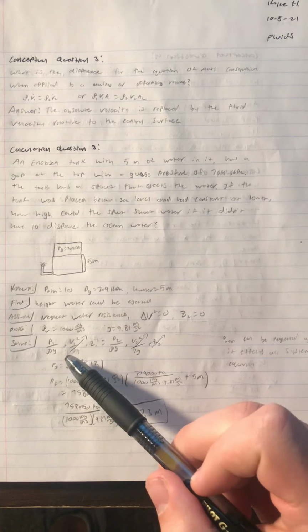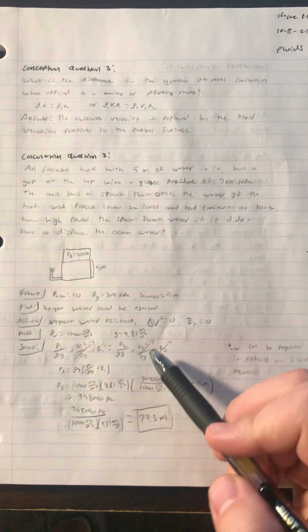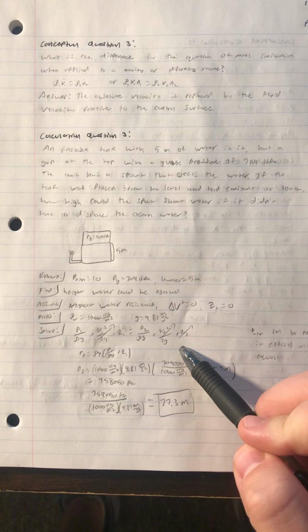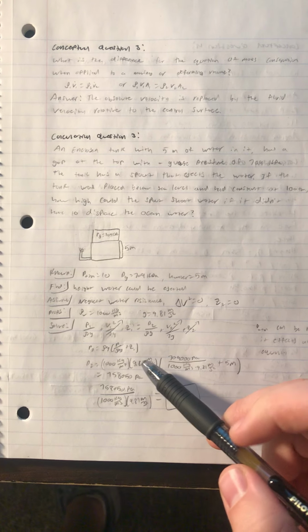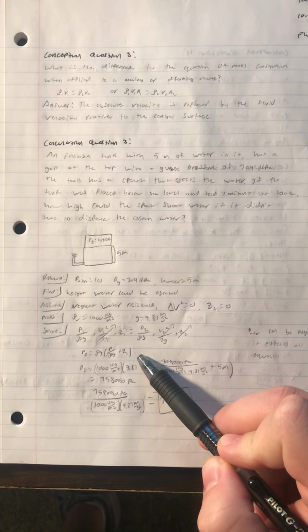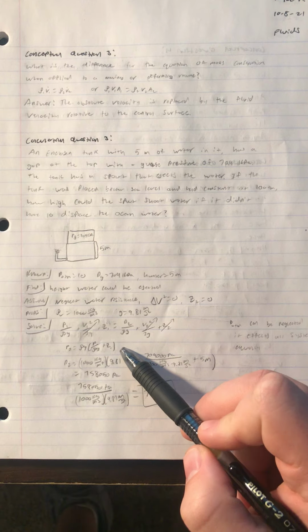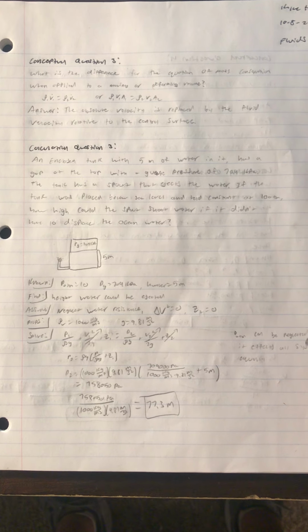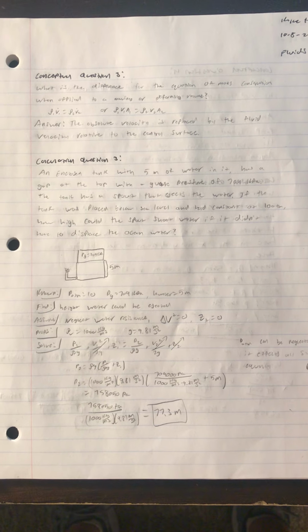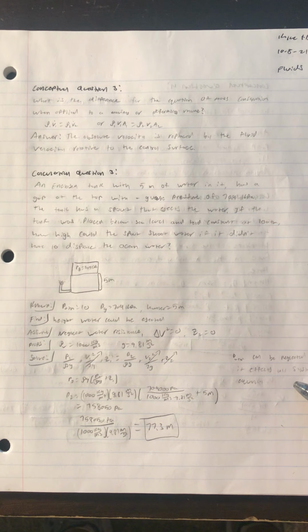So we go to Bernoulli's equation, knock out both velocity terms and the second z term, then solve for P2. The big assumption in this one is that because the atmospheric pressure is acting on all systems the same, it can be neglected.